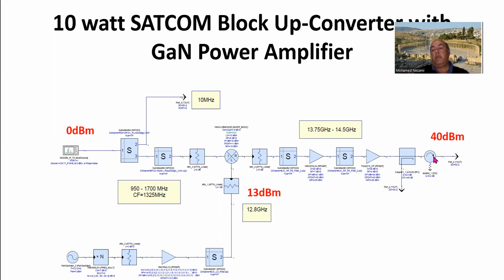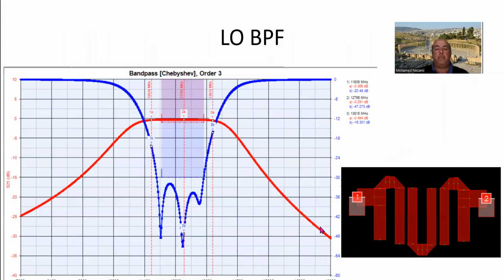If that doesn't happen, usually this also can protect you when you're in the lab or testing in production, so that if inadvertently somebody opens this or shorts it or somehow turns this system on while assembling the waveguide assembly part in here, or the power meter in here, it will protect you from reflection back that will damage the power amplifier.